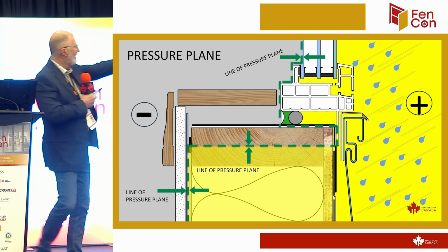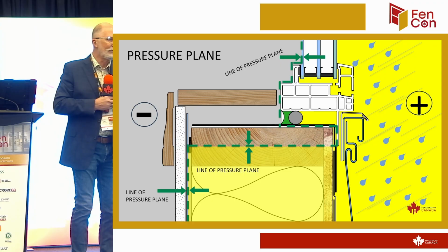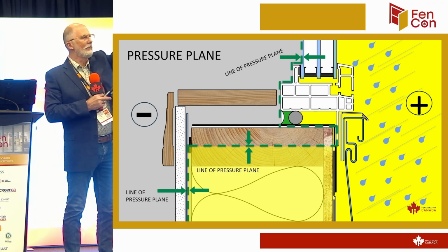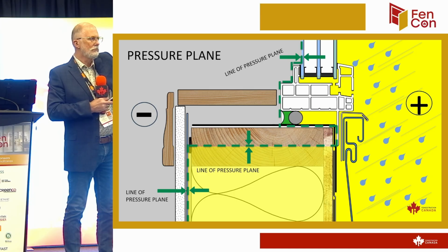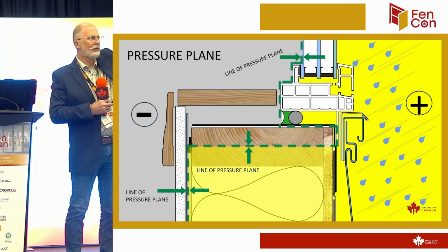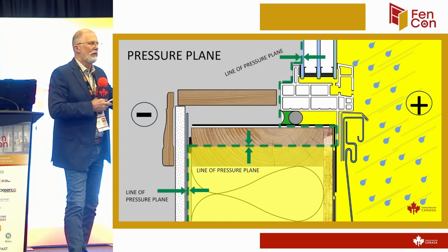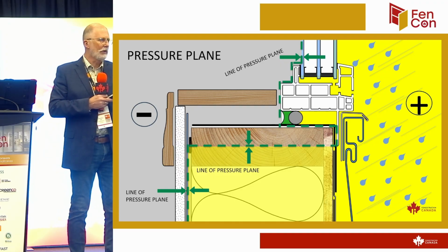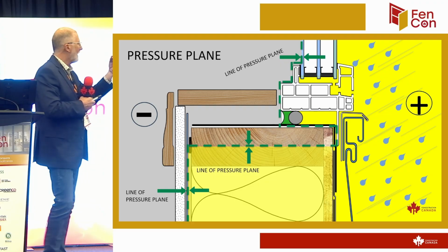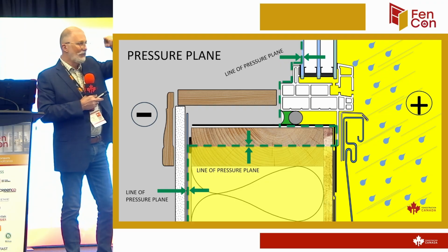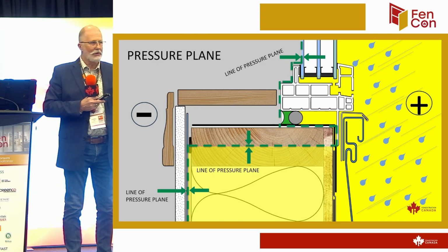Well, no, because this is on the inside. This is 2 inches in from the sheathing. Even at the top, it's 2 inches in from the sheathing. It's all the way around four sides. And whether you use backer rod, whether you use spray foam and just control and don't fill the whole cavity, right? It's not that you can't insulate the cavity. It's don't insulate it so full that the water that gets in there can't move its way around and drain back outside.